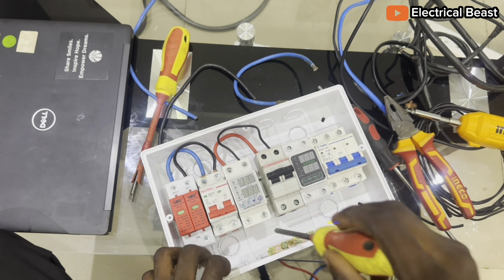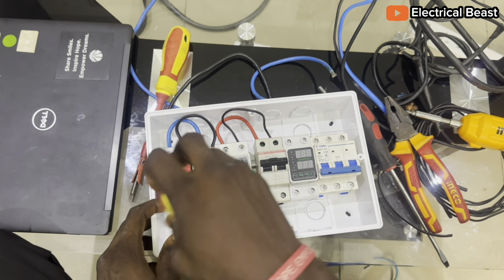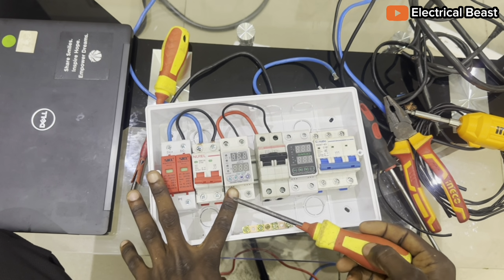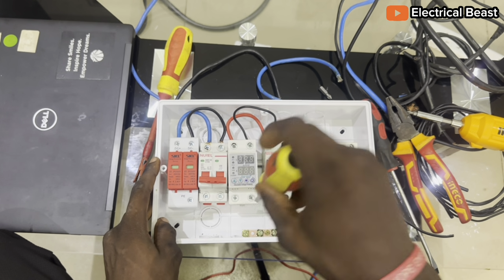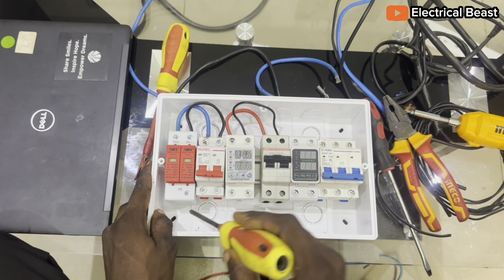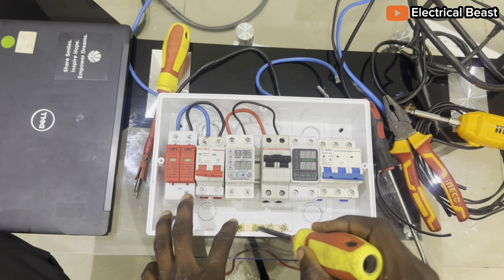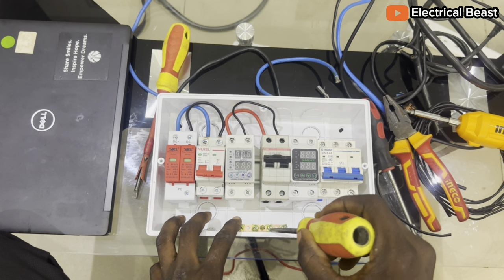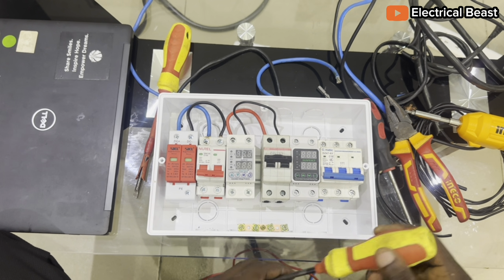Now it means these are earth terminals for the AC surge, for the DC surge, for the AC surge. Assume that this one is non-existent. So these are for the AC surge. So we can assume these are the earth bar. We'll connect all of these earth terminals to the earth bar here, so they can be at the same potential. Okay. Now, this is where it gets tricky.